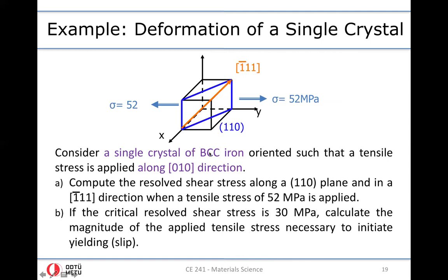So we have a single crystal where the tensile stress is applied in the y direction, the 0, 1, 0 direction. So in part A, we are asked to compute the resolved shear stress along the 1, 1, 0 plane and in the minus 1, 1, 1 direction when a tensile stress is equal to 52 megapascals.